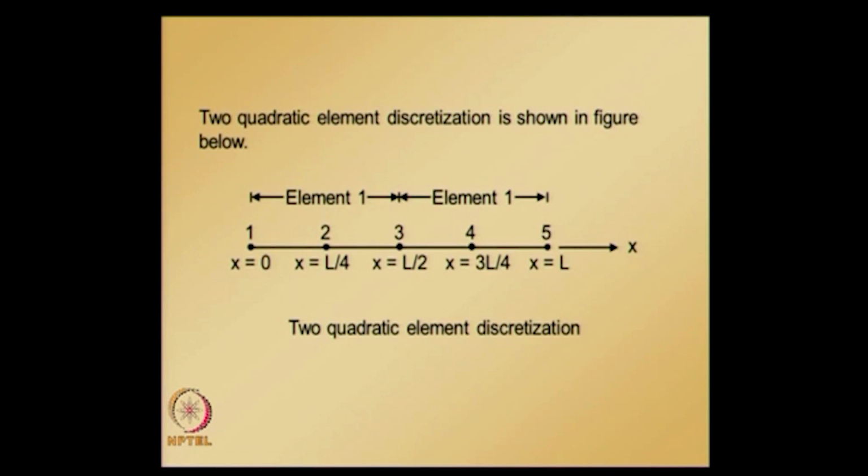You can notice that for both elements 1 and 2, the lengths are the same, and the positions of the nodes locally are at the same distance from each other. So, element equations for element 1 and element 2 are going to be the same, since EI is constant.